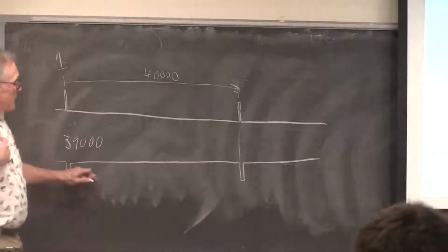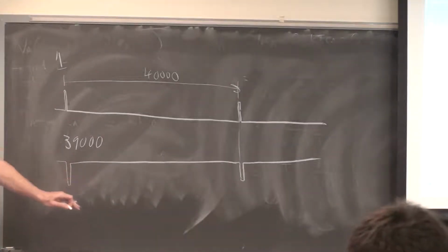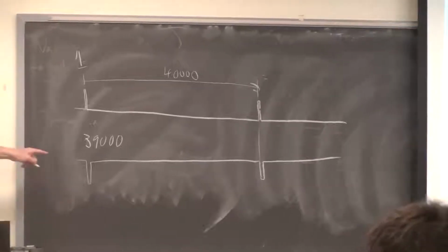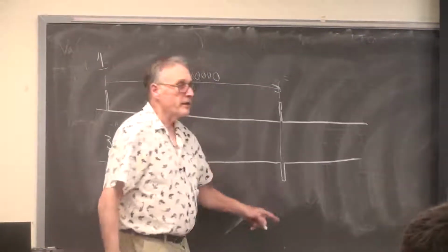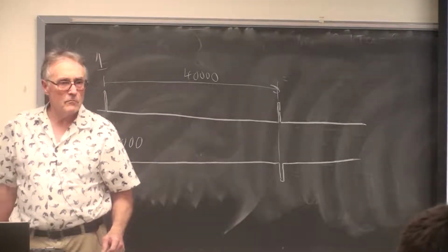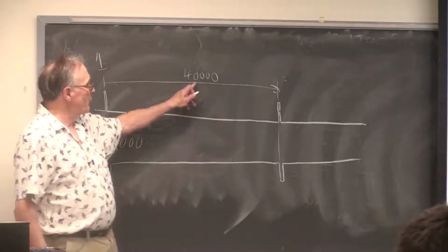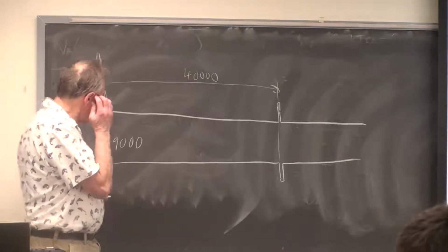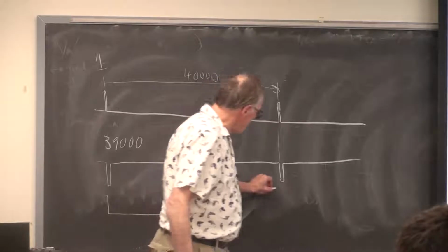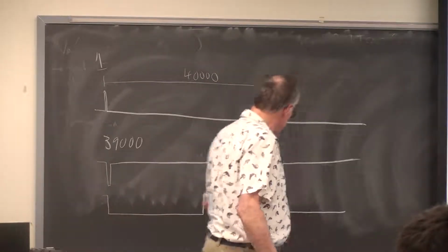In other words, the output of the PWM is going to be high most of the time, and so averaged over 1 cycle, the output is going to be very near 3.3 volts. You set it to 20,000, and you're going to get a 50% duty cycle square wave.